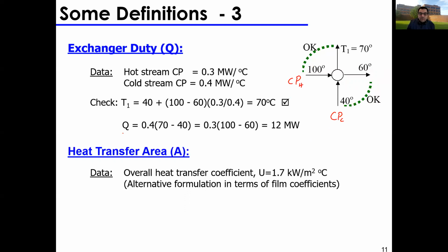And the way to calculate your heat duty is just CP delta T, right? And CP hot delta T hot must equal CP cold delta T cold, right? If they're not equal, then something's off. Take a look at your calculations, see your numbers. Maybe the CP value you're using is wrong. Maybe you missed something with the delta T units. Double check all of this stuff. But the heat lost from this stream should be gained by this stream, right?